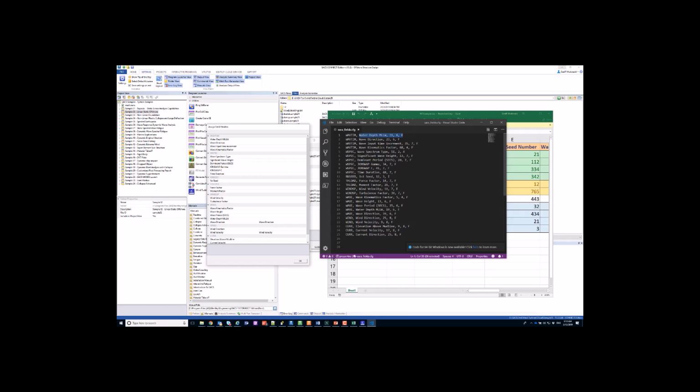Here we are allowed to set some default values if the other values are not modified. But here we can select whatever header we want. So water depth we can set as water depth. We can set the wave direction as wave direction here. I don't think we're going to use a time increment, so we'll just leave that blank. And I don't think we have a wave kinematics factor. So those will just be using whatever is from the configuration file.